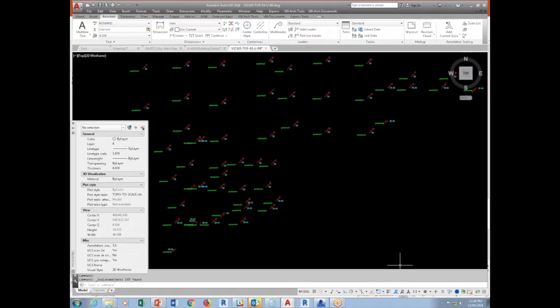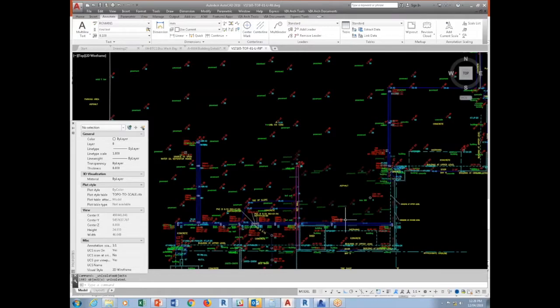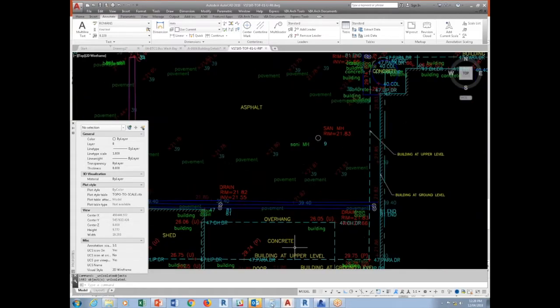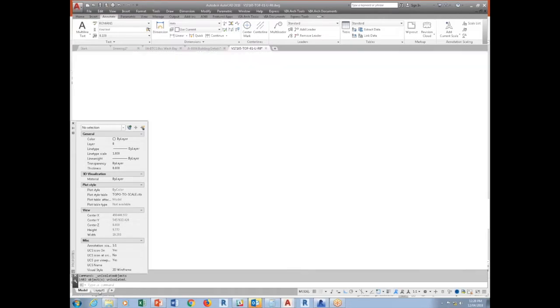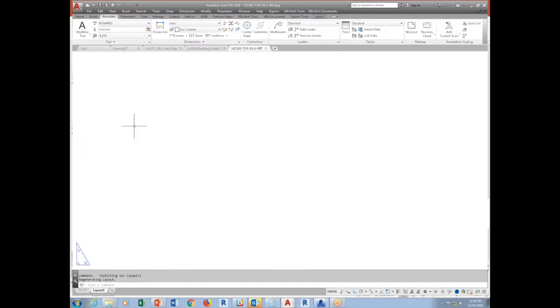So let's say I'm going to do that. Okay, now I hide that object. This is only temporary, then you can just change it back and say end object isolation. I use that a lot. Like if you are using Revit and then you go back into AutoCAD and it's like, oh, where are all these tools similar to Revit? That's a couple of similarities with Revit that you could use. Some of the tools, model, paper, I'm pretty sure you guys know all this, so I won't go into it, and then you can always create new, some other stuff.